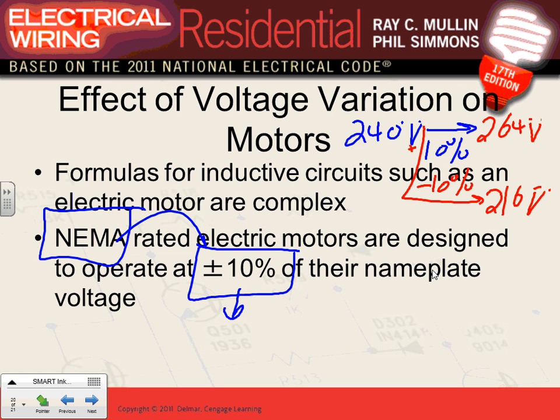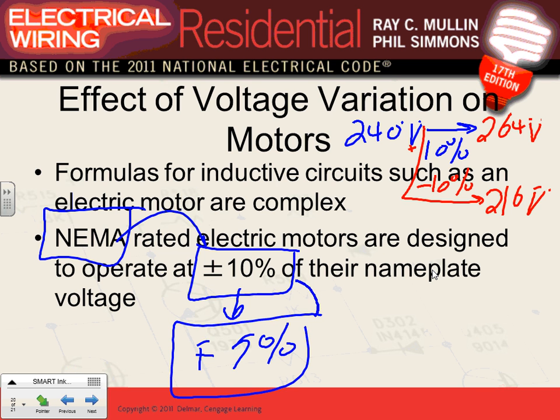Voltage drop. That has to do with the voltage drop too. What's the maximum? 3%. Well, with a branch circuit, 5%. So the code goes half of this. The code wants to force you to do half of this. So what's the code? This is plus or minus 5%. Right? So that's where the voltage drop comes in, usually minus, of course, the voltage drop.